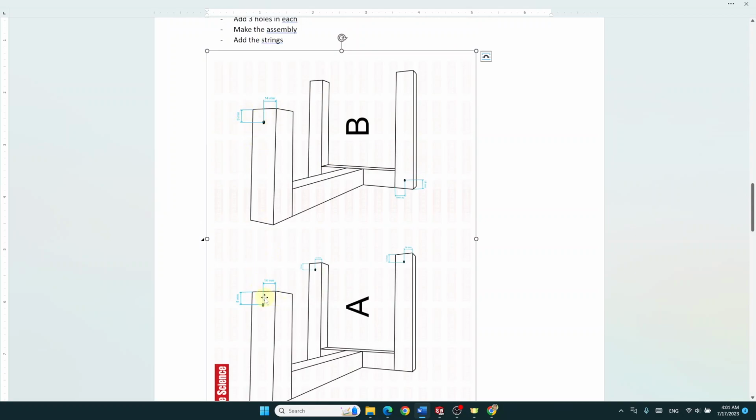The hole on the smaller part that's going like in the middle is at 14 and 8 millimeters, both of them. So let's do this hole first, and after that I will save the two parts with two different names and make the two holes. So we have dimensions for the hole. I will make a little hole of, let's say, a diameter of 2 millimeters. And we have 8 millimeters and 14 millimeters.